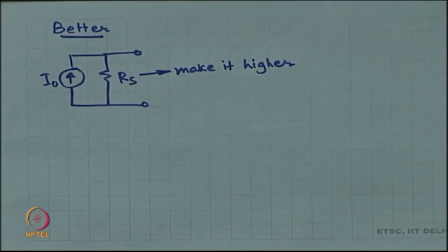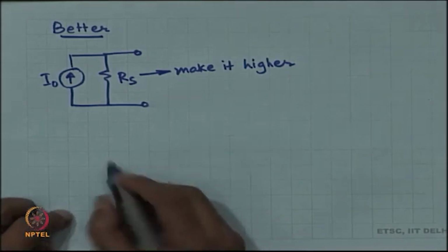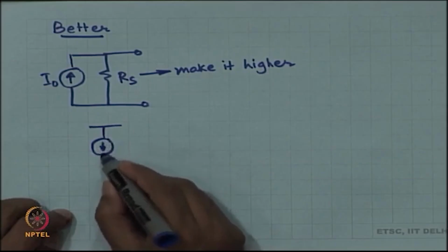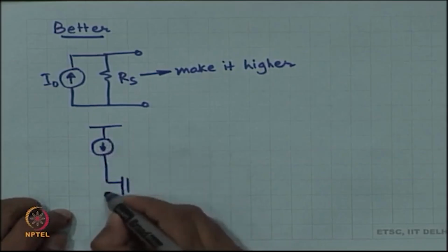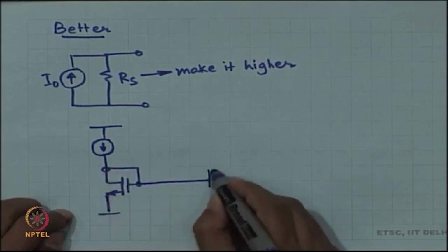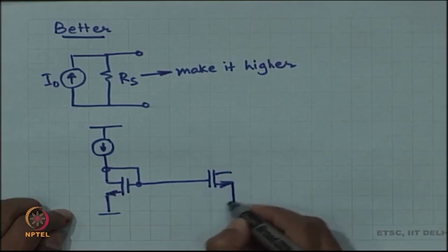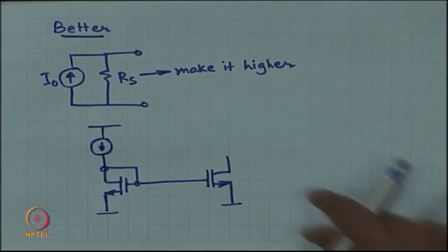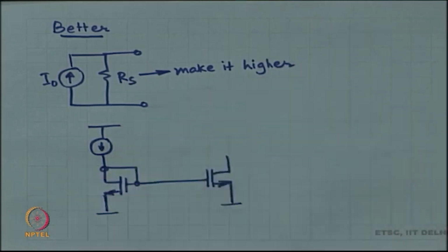How will you do that? How will you get a higher impedance? By adding a common gate stage, right.